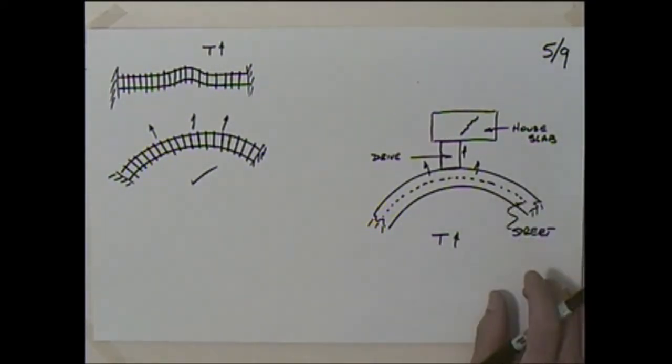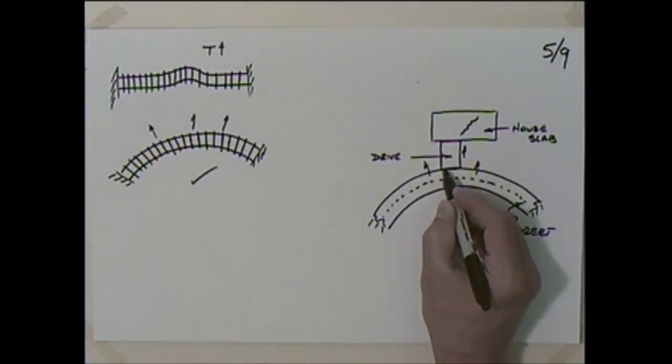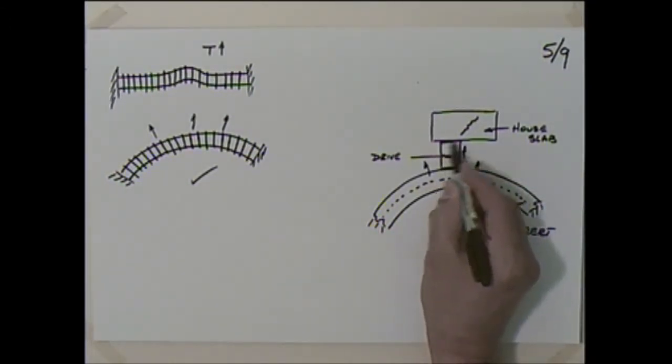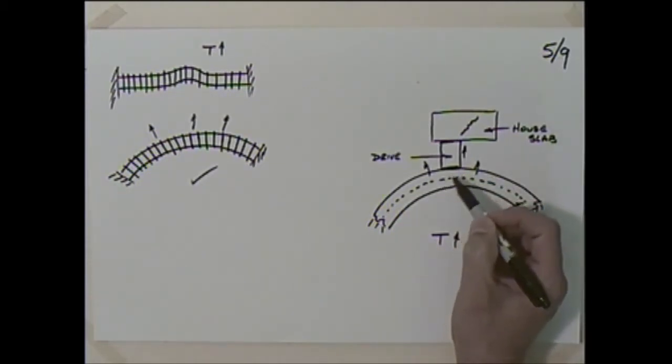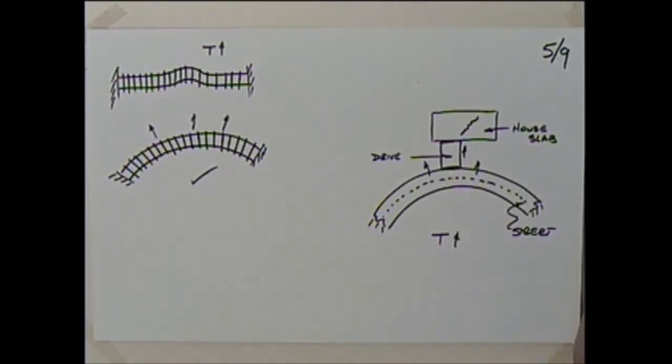So that's not super common. A lot of times there'll be enough expansion joints in here, or the geometry is not such that it pushes just right. But it's something to think about. Unconstrained expansion can tend to be a problem. So it's always hard to figure out who would be responsible in this case. Everyone's going to be pointing their fingers at one another about whether they put enough expansion joints in, or if the street should have moved. Hopefully the street doesn't move enough to now be on someone else's property. But anyway, something to think about.